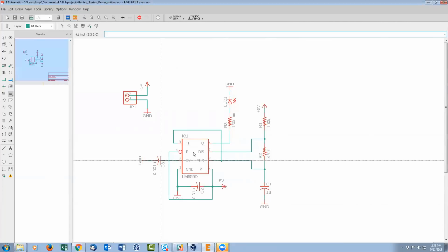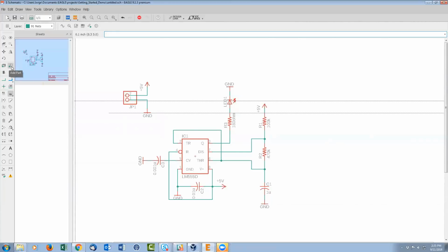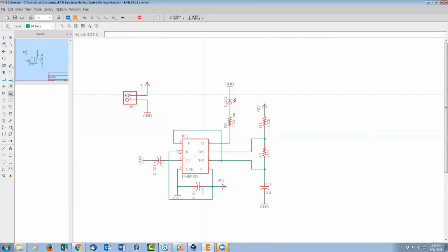So while you do that, Jorge, he's adding values, but we have a question in regards of showing the supply library. Basically, what he does is that he uses the add command again, just like if it was any other part. But you go ahead and select the supply library. Now there's 2 supply libraries, 1 and 2. The one that he used in this case, if I'm not mistaken, was supply 1.